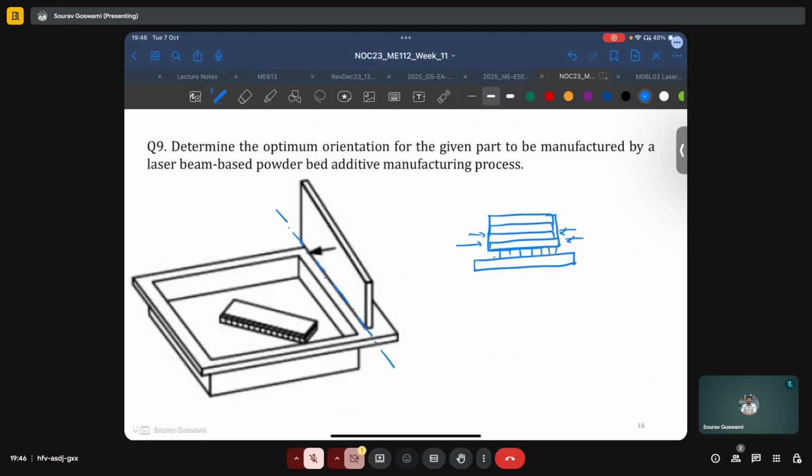So what we can do instead is raise one end, or if we look at a 2D view, we can tilt it like this. And by doing this, in each layer, because the slicing will still be planar, we are now printing differential surface areas rather than prismatic cross sections.